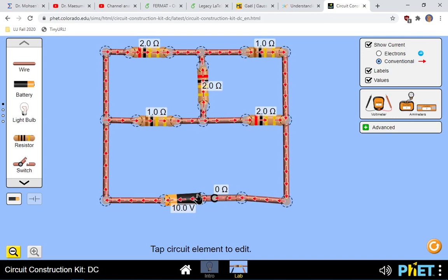Okay, so what was the purpose of the Wheatstone bridge? It's for, we said, measuring the resistance of an unknown object. In a Wheatstone bridge, one of these four elements is going to be a variable element whose resistance you can change. And what happens is that as I change this resistance here, at some point there will be no current going through the bridge.